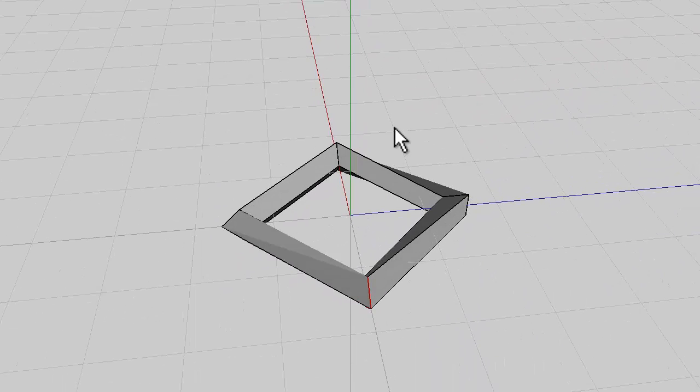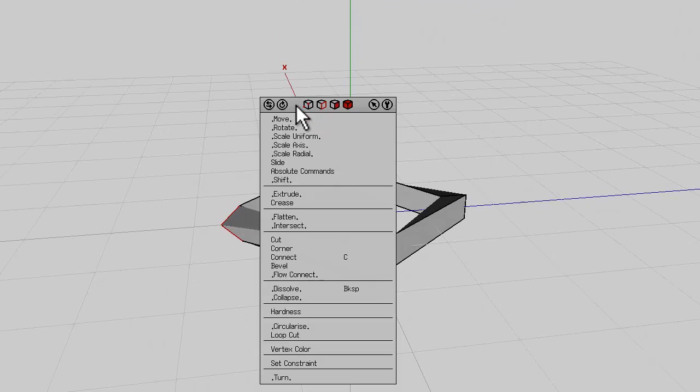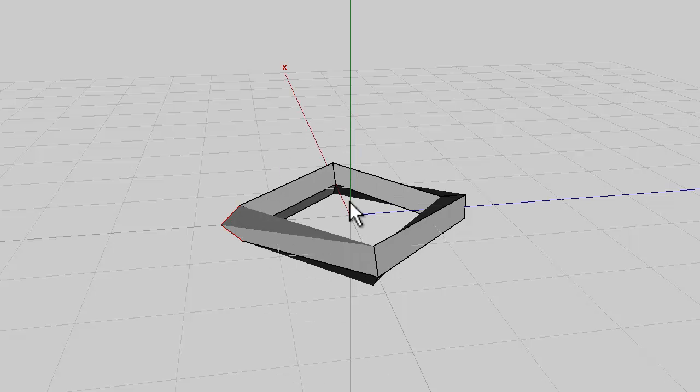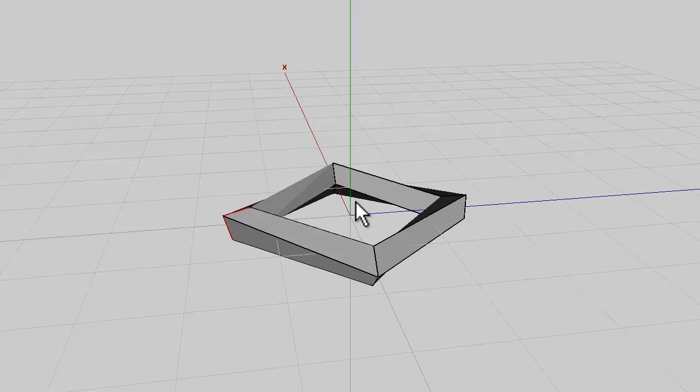Right, move around the object now, edge selection, select the edge, press L for loop, right click, rotate. We're back on the X axis now, but the sign's going to go in the other direction because we're looking from the other direction. So select the X axis, work out which is clockwise, go around 45, 90, 135 is the next step.